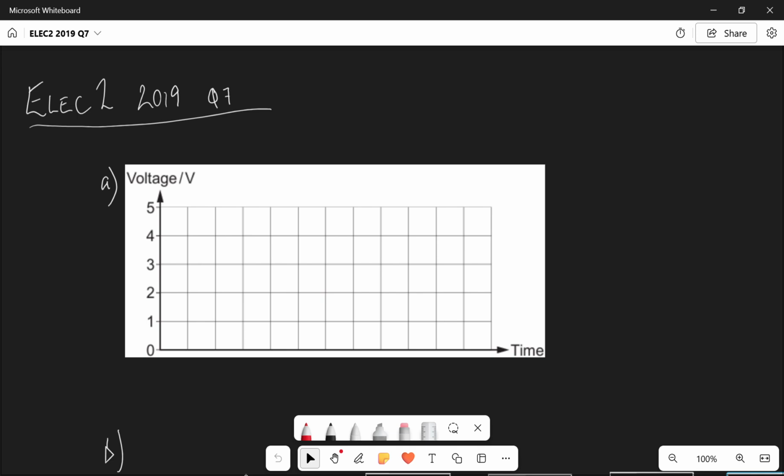So we've got our varying analog signal, we've got our sampling clock, and we've got 3 samples that need to be taken. Now for PAM, for each sample, the height of the signal is equal to the amplitude of the PAM output signal at that sampling clock instant.